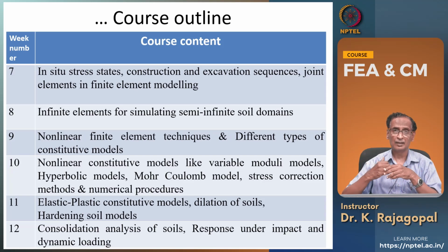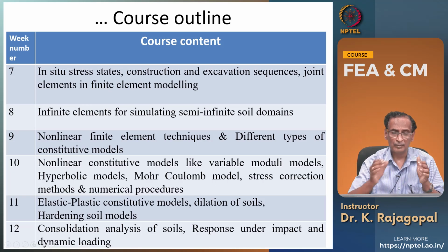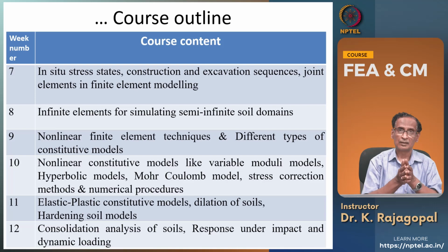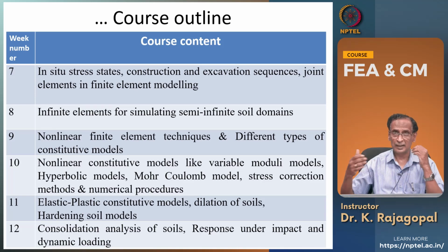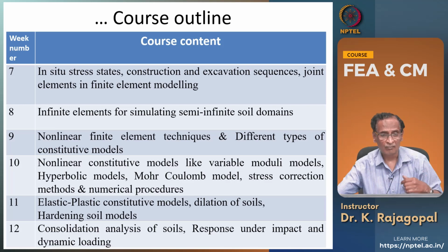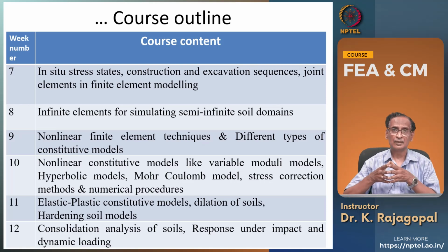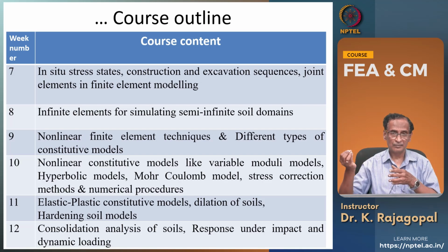Sometimes our initial earth pressures could be very, very high, especially if we are dealing with any over consolidated clay, and in such cases if you make any excavation, you have to expect significant release of stresses that might cause problems to our neighboring buildings or our own support structures. Then we will be dealing with the joints and the joint elements, or the weak joints within the materials, that's the fault planes and so on.